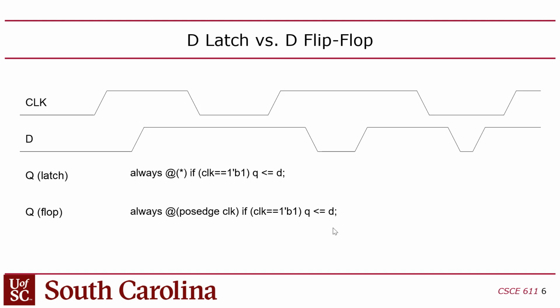Okay, so the problem is that you don't want to ever use latches because latches complicate timing. FPGAs can support latch behavior, but if you want to maximize your clock rate, you want to use flip-flops. Make sense? So you should avoid latch behavior in your code unless you really want it. But in this class, you should avoid it.